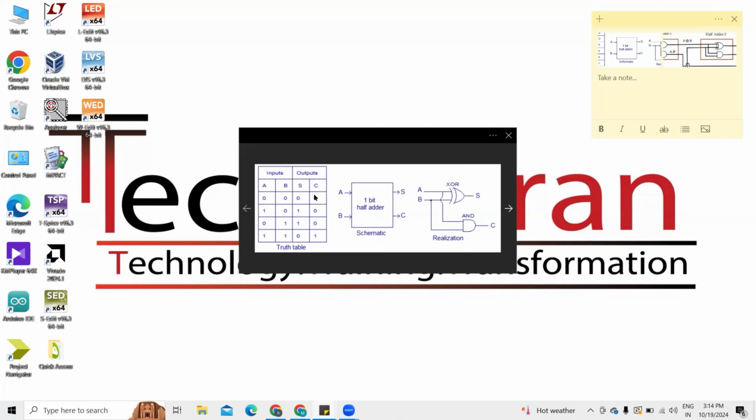Similarly, if you observe the output combination of the carry, the values are 0, 0, 0, 1. This output combination we get from the AND gate. So to get the value of carry, we need to use one AND gate here. Clear? So this is all about the half adder circuit.